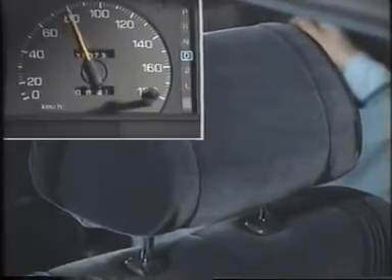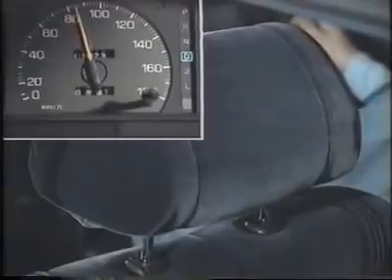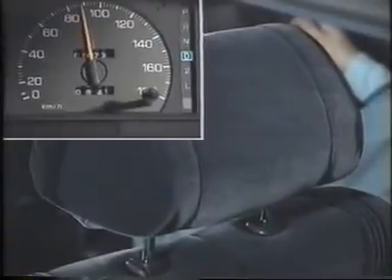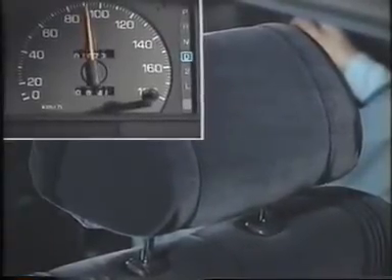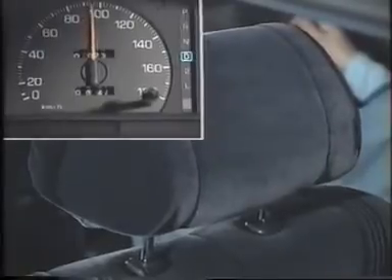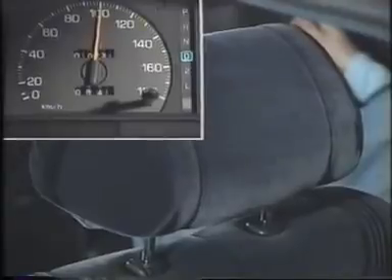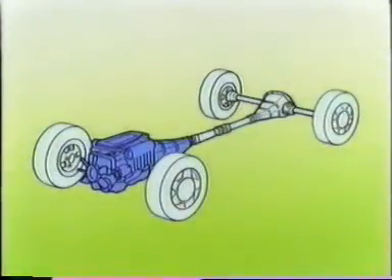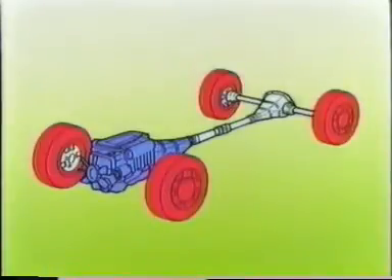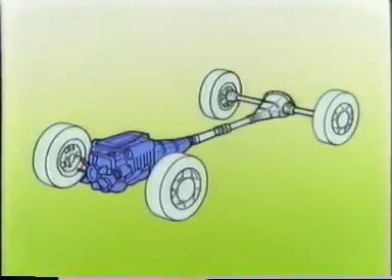We know that the vibration increases as the vehicle speed increases. It appears then that you should suspect a component whose rotational speed increases as the vehicle speed increases. It could be the propeller shaft, the differential ring gear, the drive shafts, or the tires, or some combination of these.